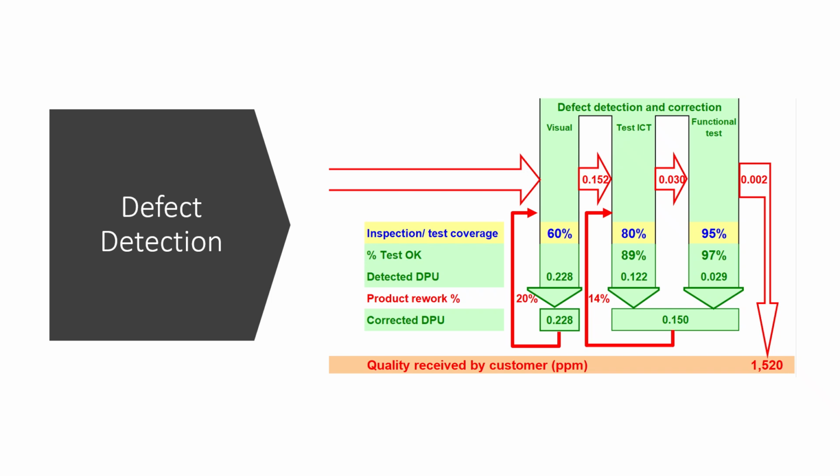Visual inspection operators, if they are qualified to do rework, will report the defect and correct it, otherwise the board needs to be taken out of the stream and sent for rework. In this example, we notice that 20% of the inspected boards need to be reworked, so we can calculate the workload required to do this. We must also be aware that the 20% reworked boards will join the stream again and be re-inspected, so this means that the visual inspection workload will be for 120% of the boards built.